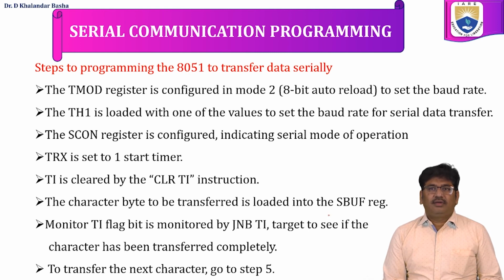TI is cleared by the CLR instruction. The character byte to be transmitted is loaded into the SBUF register. Monitor the transmit interrupt flag bit by JNB TI, target location, to see if the character being transmitted is completely sent. To transfer the next character, go to step 5.